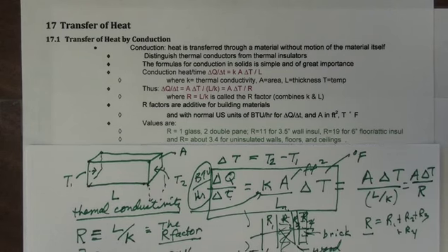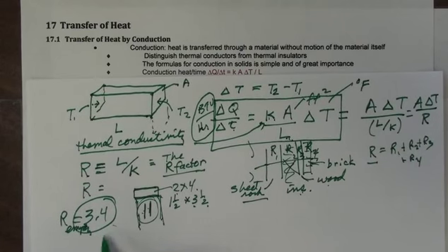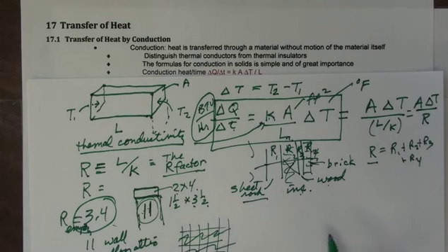And then with wall insulation, you're going to have an R of 11, and a floor or attic about an R of 19. Now what you can do is you can take your joists in your attic and you fill those with your insulation, 6 inches. Then you can come back and put another set across these, and you got an R19 twice. And that's normally what is done today because energy prices are so high. We doubly insulate our ceilings because the attics get so very hot.